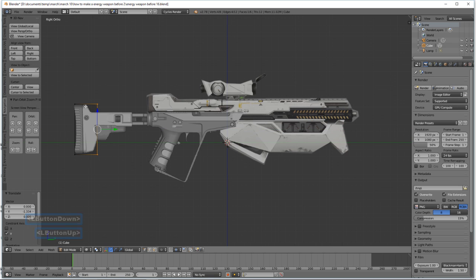So generally we have this right here. We can see how this lines up here, this lines up here, but we have this right here. So we can hold Control and, while holding Control, press R to put a loop cut in. See that line that just popped up? That line is our loop cut. If I left click one time, the loop cut is partially locked in, but because I only left click once, I can move it. So I'm going to move the loop cut up just like this.